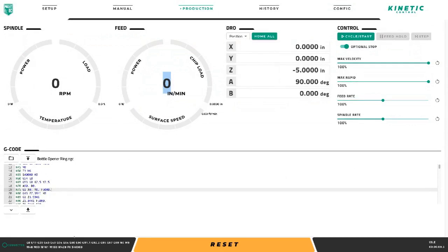Your commanded feed rate is down here in your active codes. So that F0 currently, we don't have an active feed rate. We do have plans to make it more present in other locations. But for now, this is a calculated one. The commanded one's down here. Same with the spindle speed. Your commanded spindle speed is down here in your active codes. This is, if you have the sensors on your machine, a calculated spindle speed.